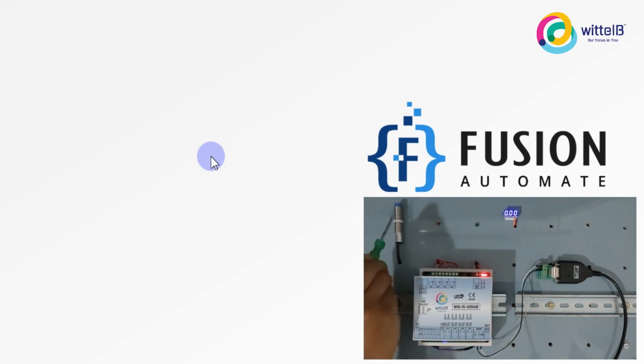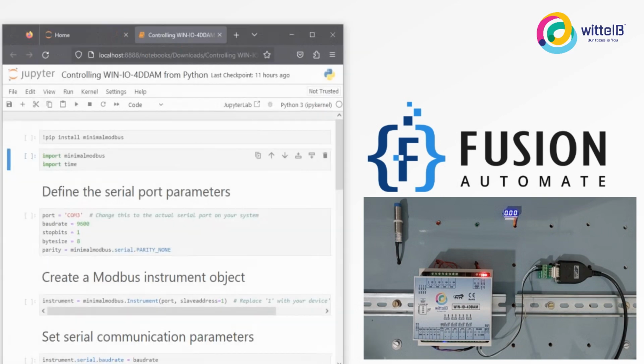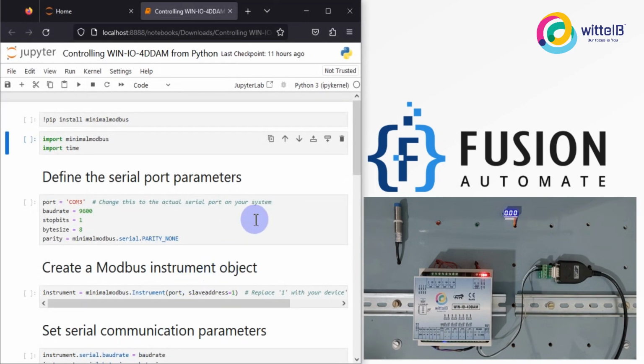This is because this is an inverted logic sensor, or you can say an NPN sensor. If there is no part present, it will give me 12 volts, and if there is a part present on the sensor, it will give me 0 volts. That is why I have to write a logic that whenever DI1 is low, I want to turn on the red LED, and whenever there is a voltage on DI1, I don't want to turn on the red LED. Everything I have written in Python, you can see here.